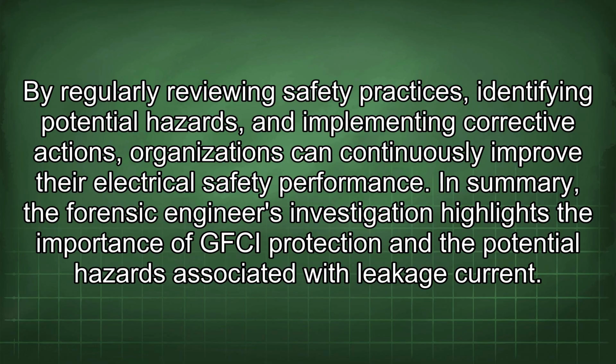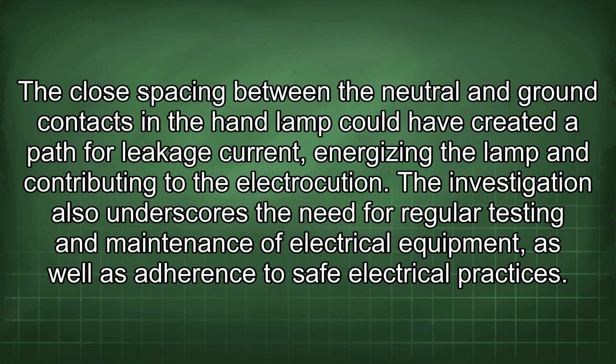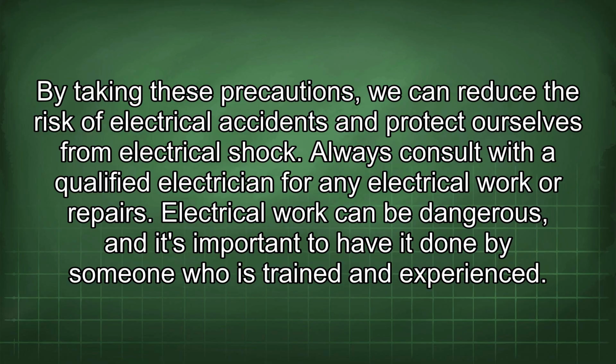In summary, the forensic engineer's investigation highlights the importance of GFCI protection and the potential hazards associated with leakage current. The close spacing between the neutral and ground contacts in the hand lamp could have created a path for leakage current, energizing the lamp and contributing to the electrocution. The investigation also underscores the need for regular testing and maintenance of electrical equipment, as well as adherence to safe electrical practices. By taking these precautions, we can reduce the risk of electrical accidents and protect ourselves from electrical shock.